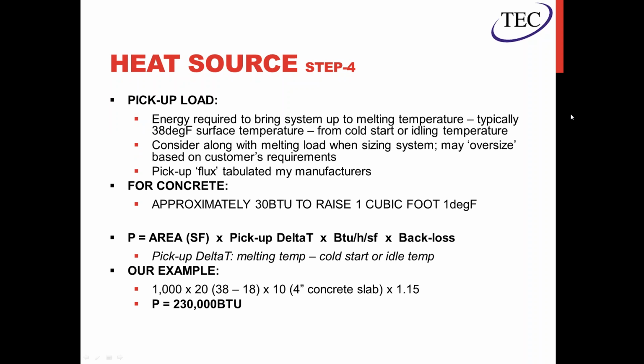So the pickup load would be the energy required to bring the system up to melting temperature, which is typically 38 degrees surface temperature, not a slab temperature. And the pickup load can either be from a cold start or an idling temperature. So we'll talk about some control schemes a little bit later, but basically you have the option to idle the slab at a median temperature to allow the pickup time to be shorter.